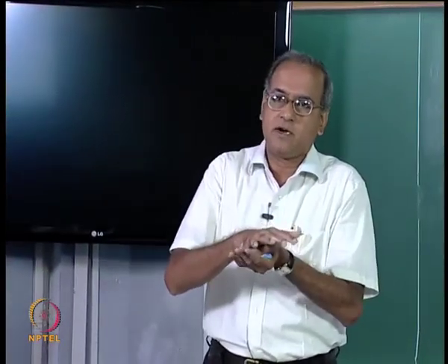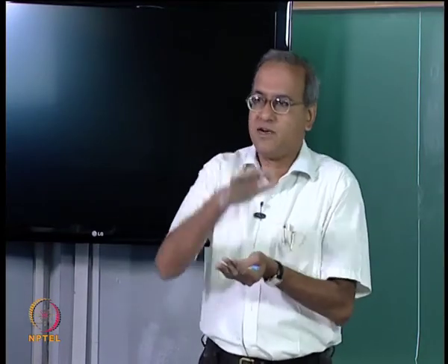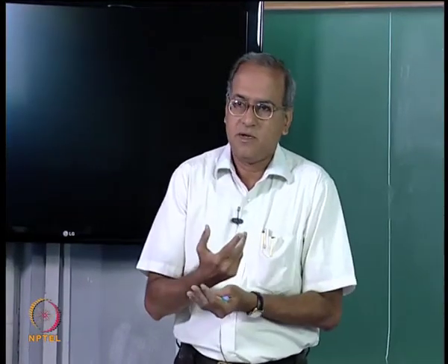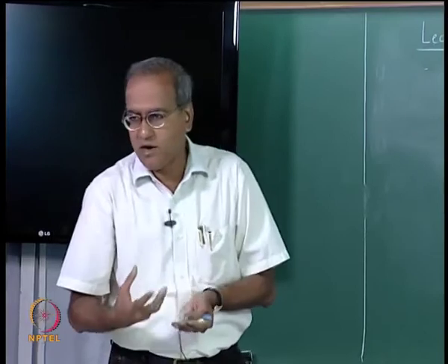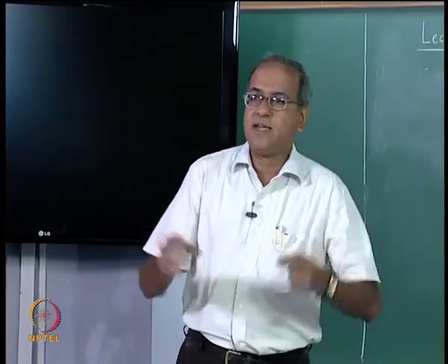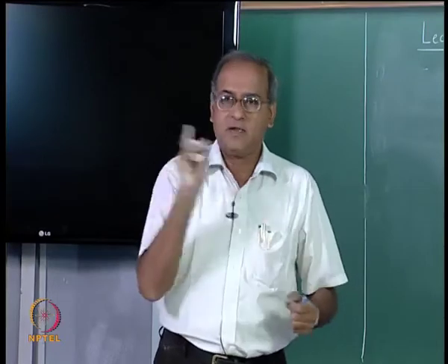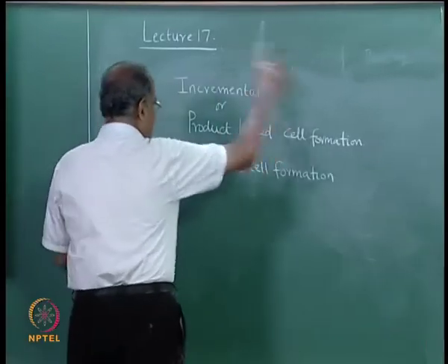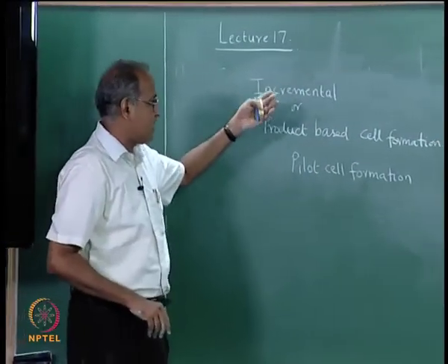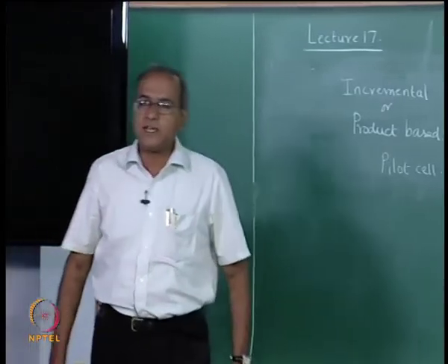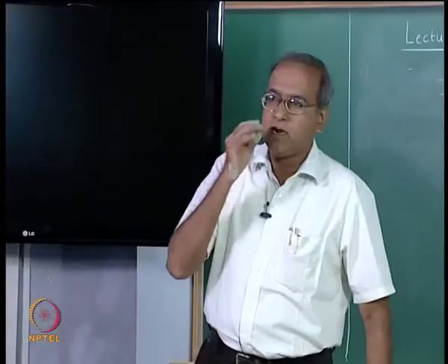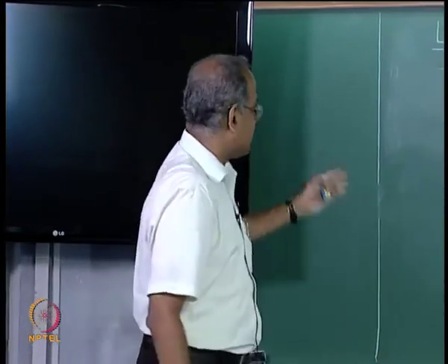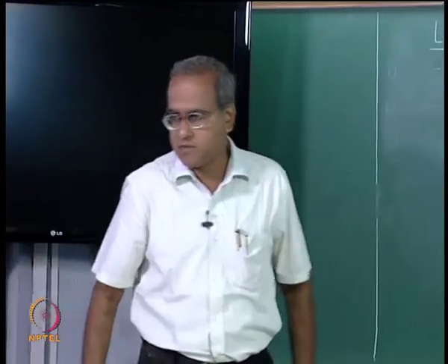This cell would be expected to produce at a slightly faster output than what it is currently doing. Therefore, newer machines will be brought in. Therefore, again the problem will be one of making one particular cell that caters to the requirements of either one product or very few products. So, we now bring all of these into the classification called incremental or product based or pilot cell, under the assumption that the volume is large and for a particular product we are going to create a cell. So, we can use the term called product based cell formation.